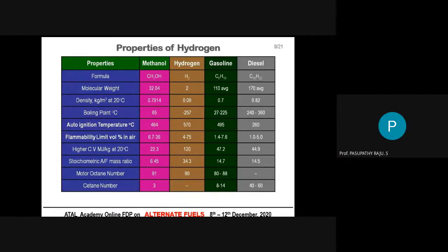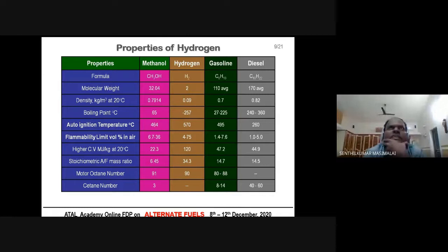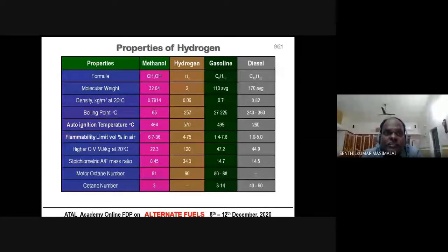Sir, you mentioned flat piston. What is flat piston? Now in a diesel engine, you will see the piston has a bowl for creating turbulence. Bowl will be there. In case of a petrol engine, you may have some kind of projections for creating turbulence inside the combustion chamber. For creating the turbulence, we will have some arrangements in the piston.